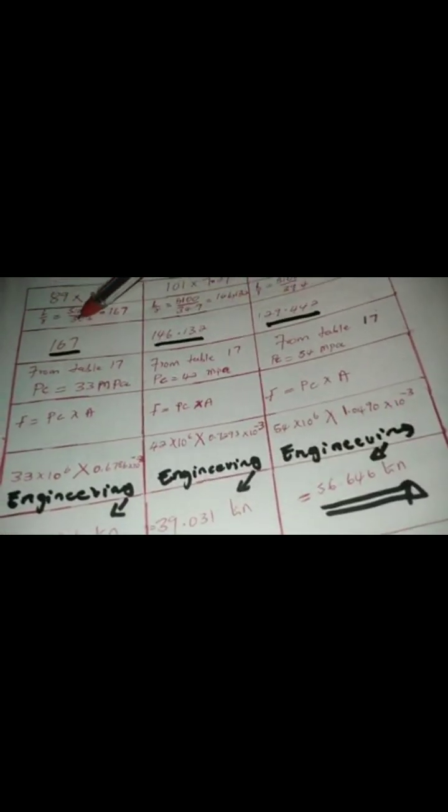That is why I substituted R with 30.6, and 5.1 is the calculated effective length. This calculated effective length, we're going to use it on all three columns. So here it's going to be 5.1 divided by 34.9, for 101 times 7.29.